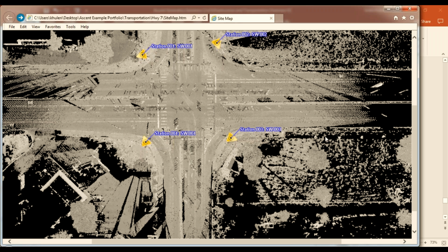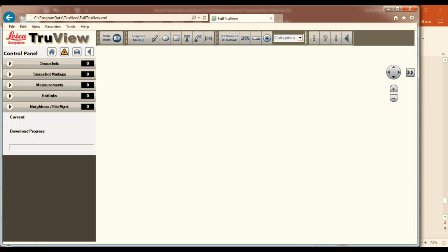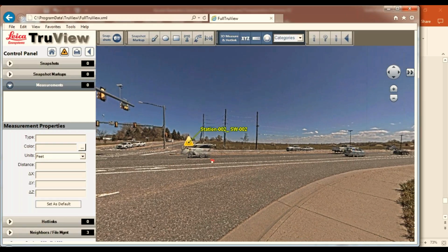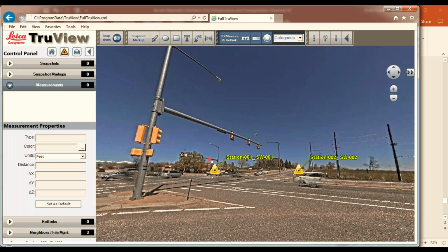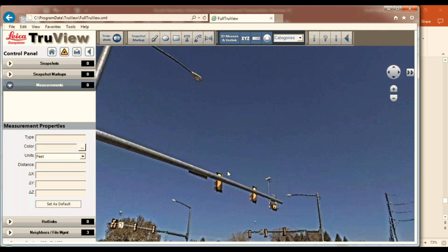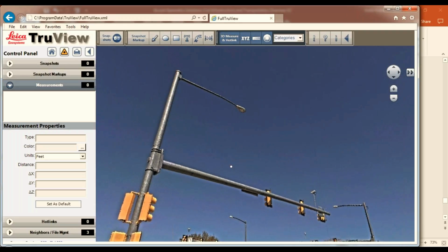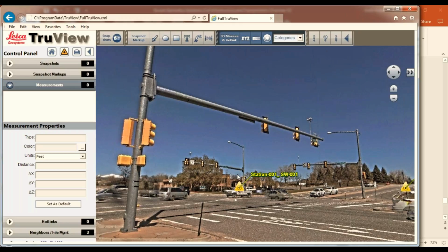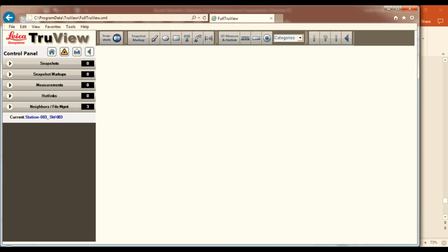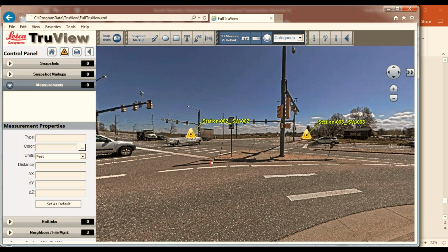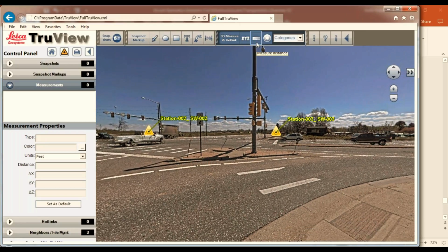Yeah, definitely. This is essentially like having Google Street View at your project location. So you can go in, you can see here's the scatter of the point cloud. You can click on the station, and you literally are going to be the head of the scanner when we're using our static scanners. An intersection is a great example here, where you can get just a level of detail. You can look up and see, is it a halogen, an LED light? You can do general inventory with it, so you can see what type of cabinets are out there, what's the condition of the markings, and again, like Keith said, this is something that anyone can just log in. It's a real colorized point cloud, so they can click measurements and they can annotate measurements, so they can say, look at this stripe here, it's worn out, it's X amount of feet wide.